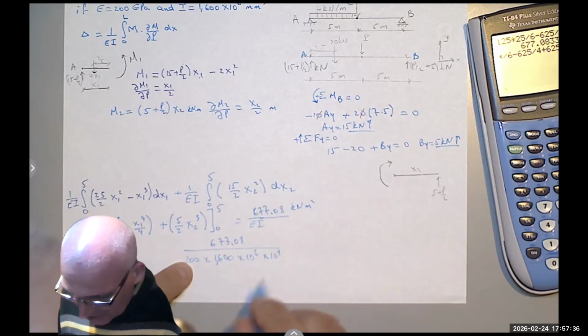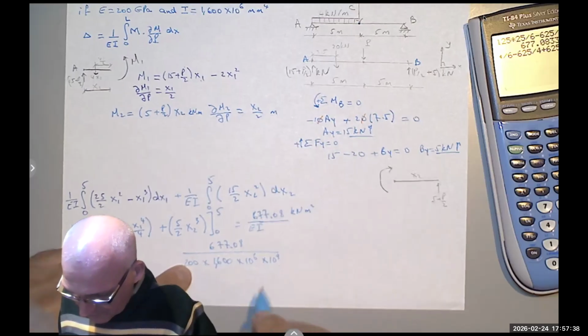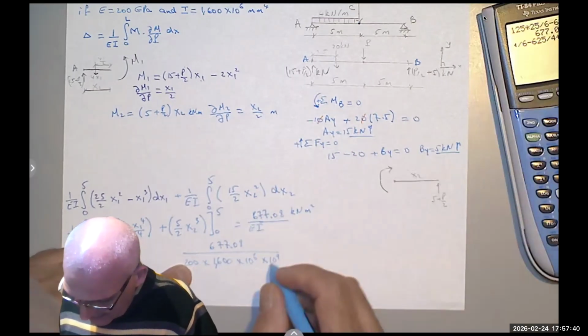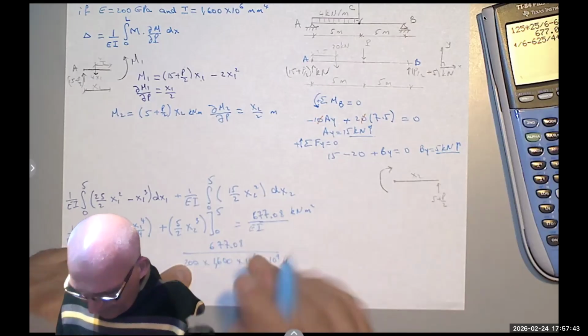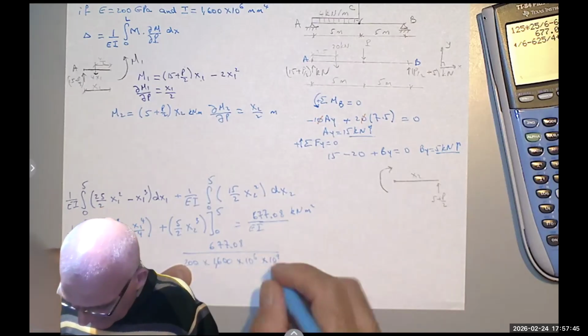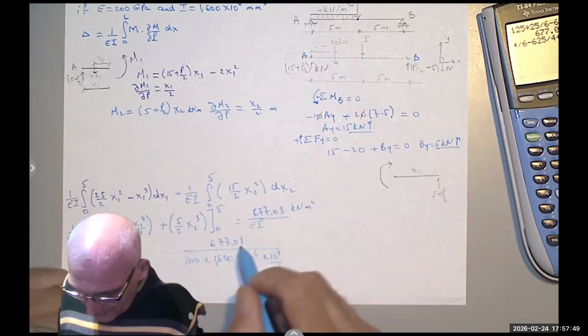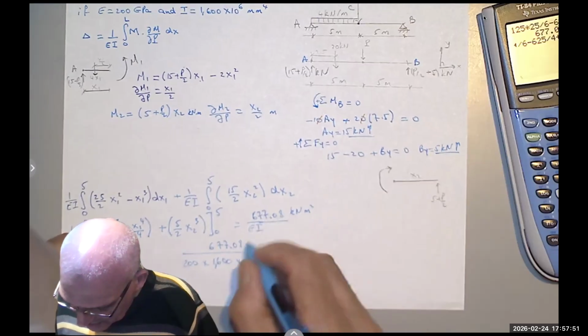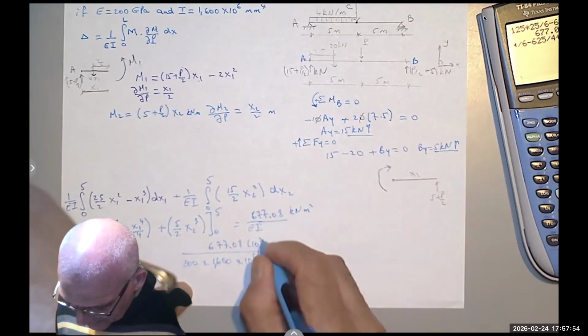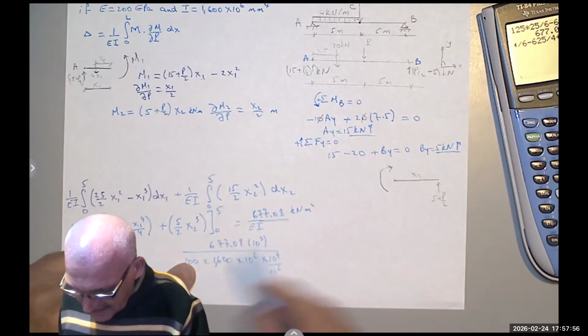Okay. So, these are per square meter. So you divide by 10 to the 6. In the numerator, I have kilonewton, so I would multiply by 10 to the third to be Newton and cancel each other.